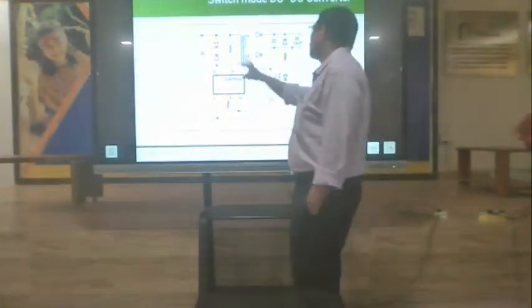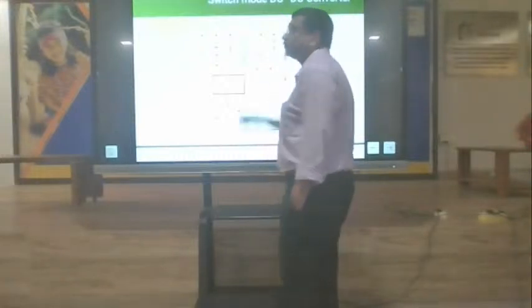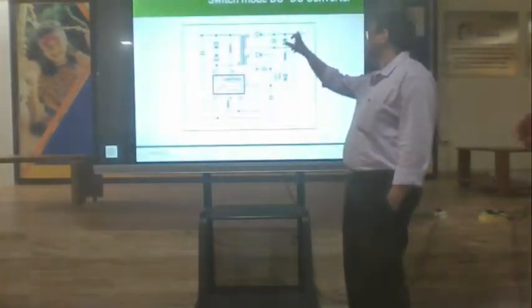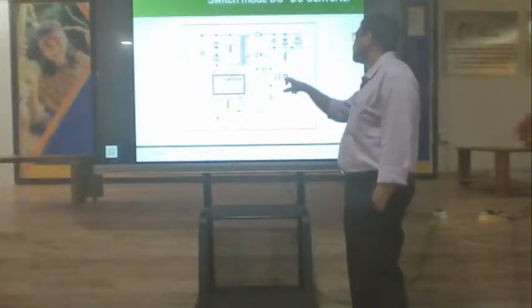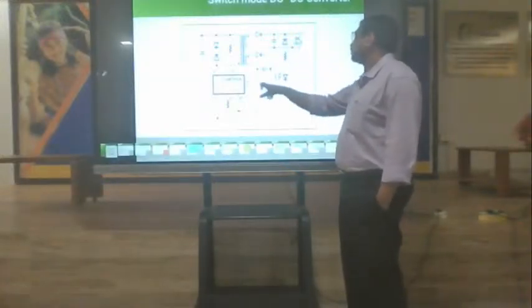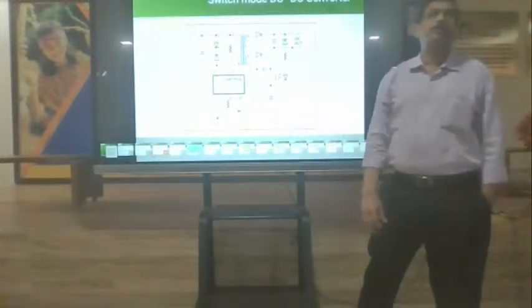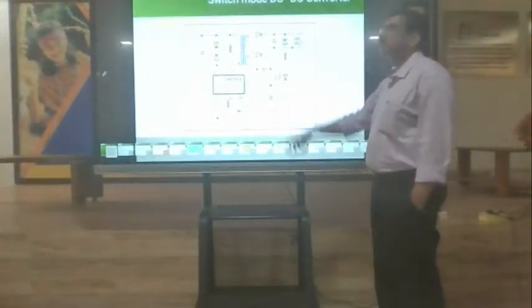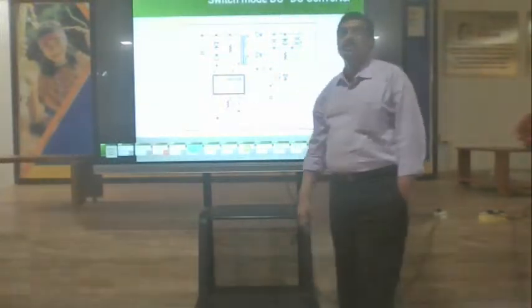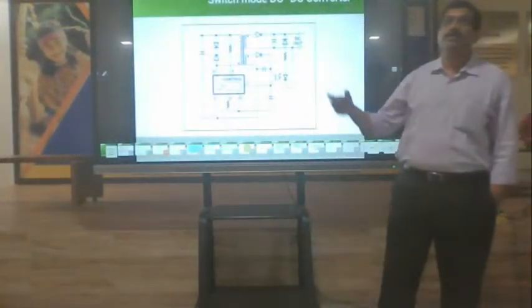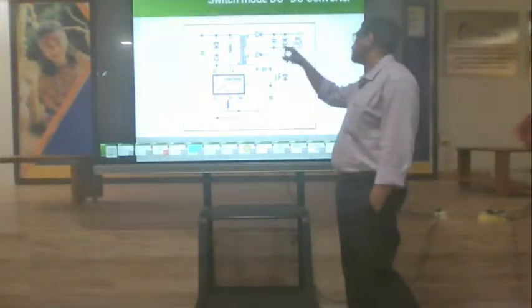At that time, the voltage will start building up. It will be checking this voltage through the feedback circuit, checking whether the output is set to the required output or not. If it is not, what will happen? It will increase the duty cycle. It will keep on increasing and then checking.